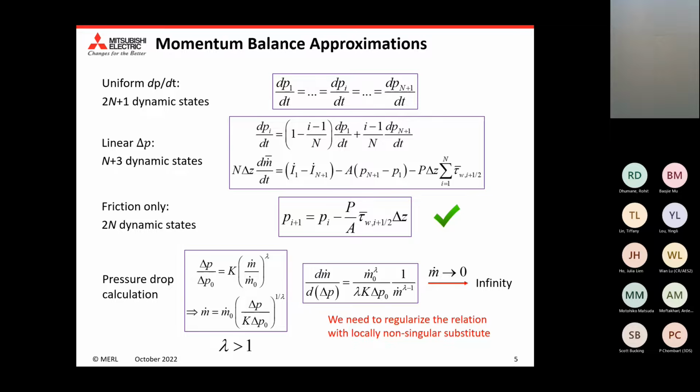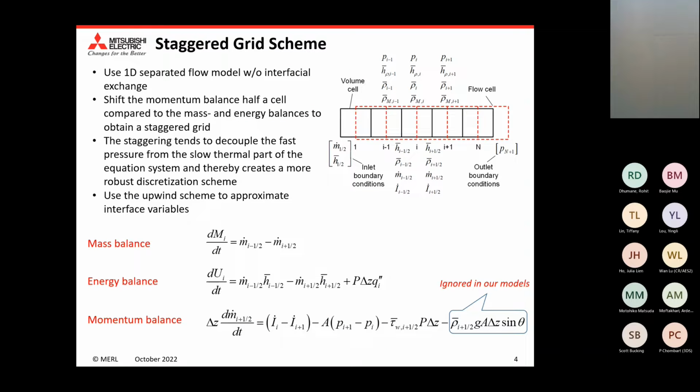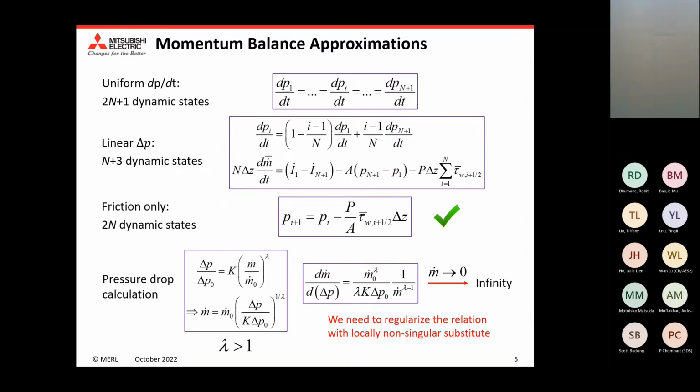If you look at the component equations here, the pressure and the entropy will be the same variables, right? We need to calculate the mass flow rate based on the pressure loss, not the other way around. So yes, you are right. If we apply the cubic approximation for this, you cannot get an inverse function at the origin. But we apply the approximation directly here because we don't need any inverse function in this relation. Because you have mass as the state, you can guarantee that the tool does not invert that equation. That's right.